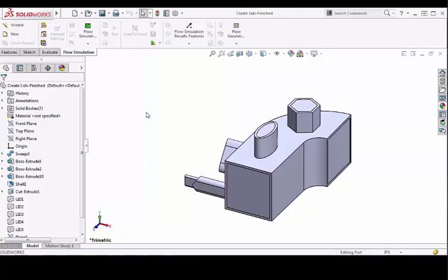The two main reasons that prevent meshing are, number one, that there are openings in the geometry that prevent SOLIDWORKS from fully defining a fully closed internal volume. Now, this would happen only in an internal analysis, and only if there are openings that haven't been closed off by lids. The second reason a model cannot be meshed is invalid contacts. An invalid contact is defined as an edge, line, or point contact between the part files, like we saw earlier. These invalid contacts prevent SOLIDWORKS from being able to calculate the internal fluid volume, and you won't be able to run the analysis. Let's look at a couple scenarios.